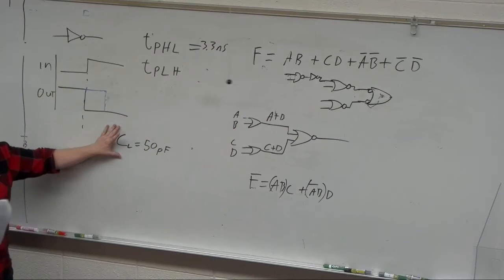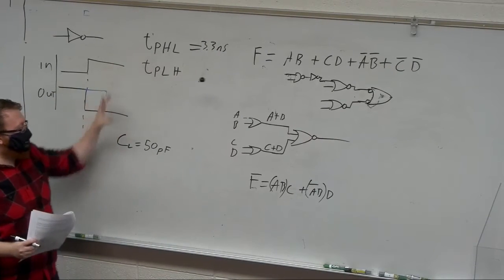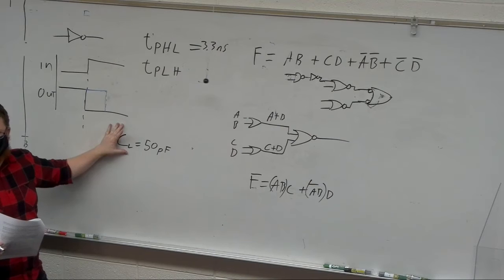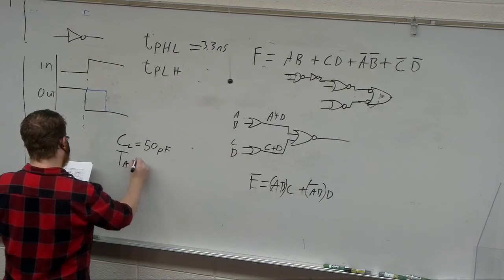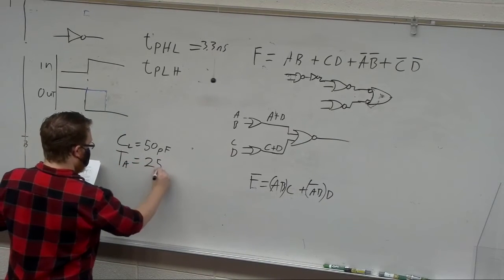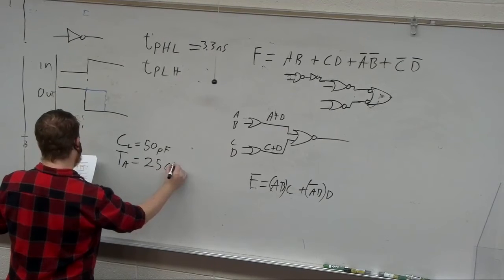It'll be defined at 3.3 nanoseconds if the load is 50 picofarads or less, and the temperature is 25 degrees Celsius.